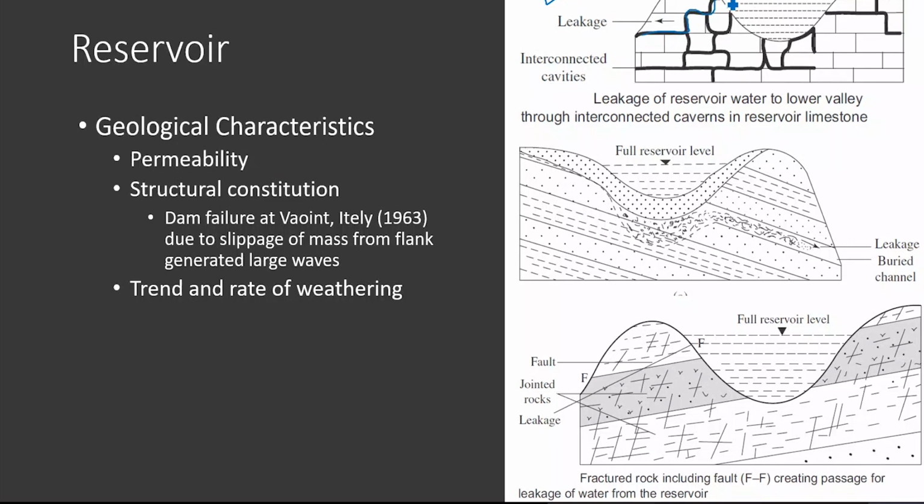cracks on them, and the water which is stored in the reservoir started getting into these cracks, and it started moving through these cracks, and it is escaping from the reservoir. So there is a huge amount of loss of water through this limestone. Okay, so this is a really unfavorable condition, but we have constructed the dam for the purpose of storing the water. Now the water is leaking through, and this we will realize only after we construct the dam.